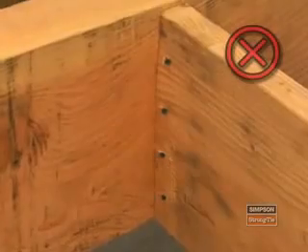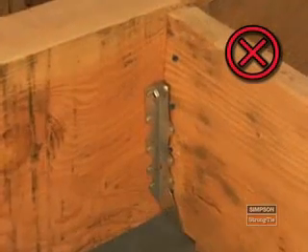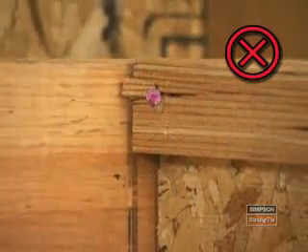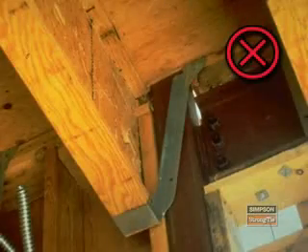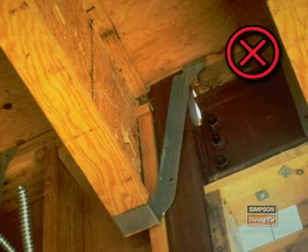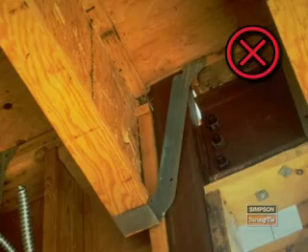Don't toenail joist to the beam or header before installing a hanger. Toenailing can cause floor squeaks and incorrect hanger installation. Don't overspread the flanges of a hanger. Overspread flanges don't provide enough side support and can cause uneven surfaces and floor squeaks. Overspread flanges can cause the joist to roll over.